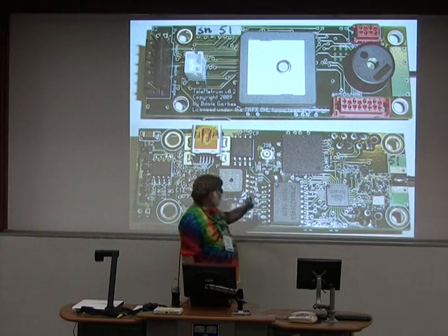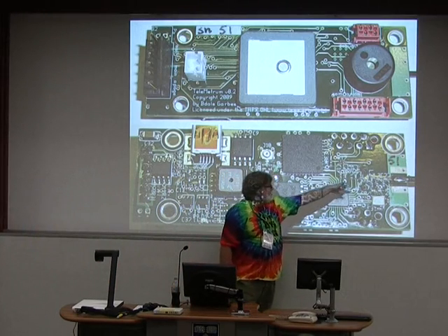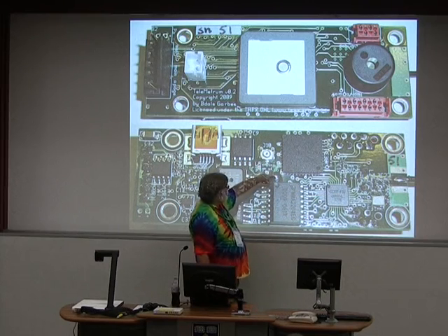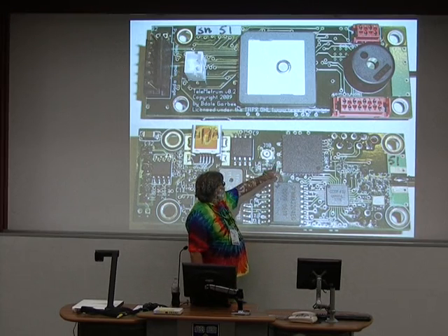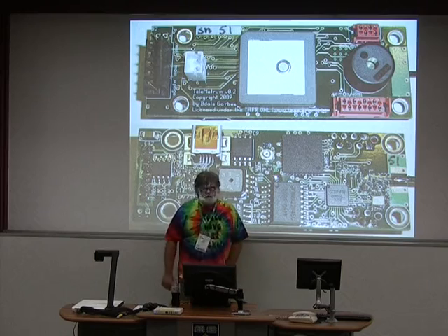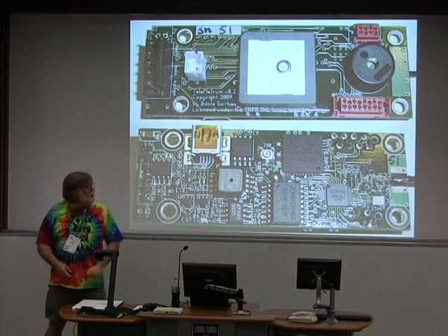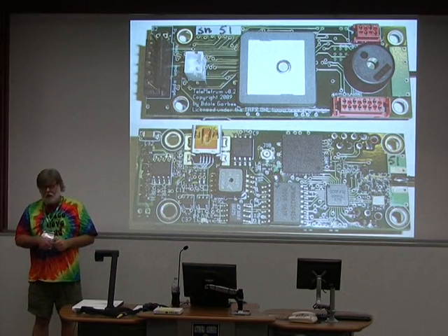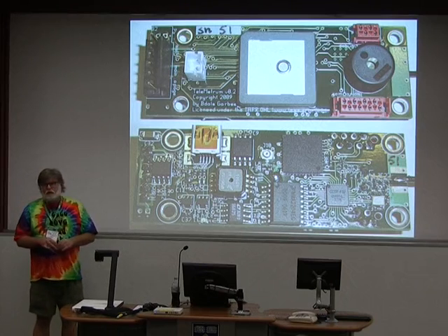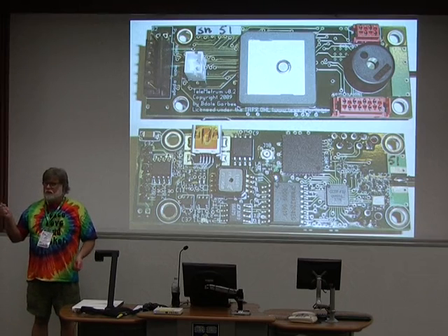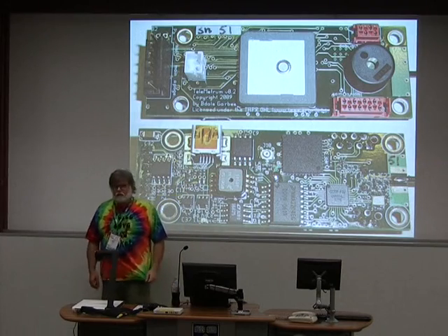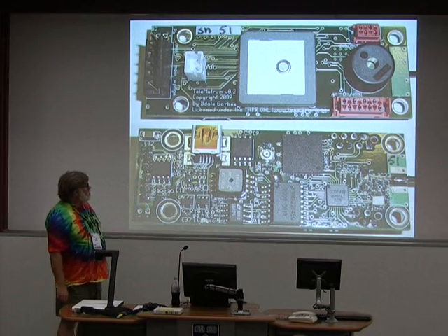And just to show you around a little bit, that's the CC1111 again with its UHF balun filter network. This is the GPS receiver. This is where the patch antenna connection comes through. And then this was a connector that I put in as a U.FL connector. A lot of GPS modules at that time, a lot of people were using U.FL connectors for connecting the antenna to the receiver. And I don't know why, but I thought it just might be the case that we might want to remote mount a GPS antenna sometimes. Having the connector on the board with a DC bias feed for it and all might be smart. And it turns out that was really important.